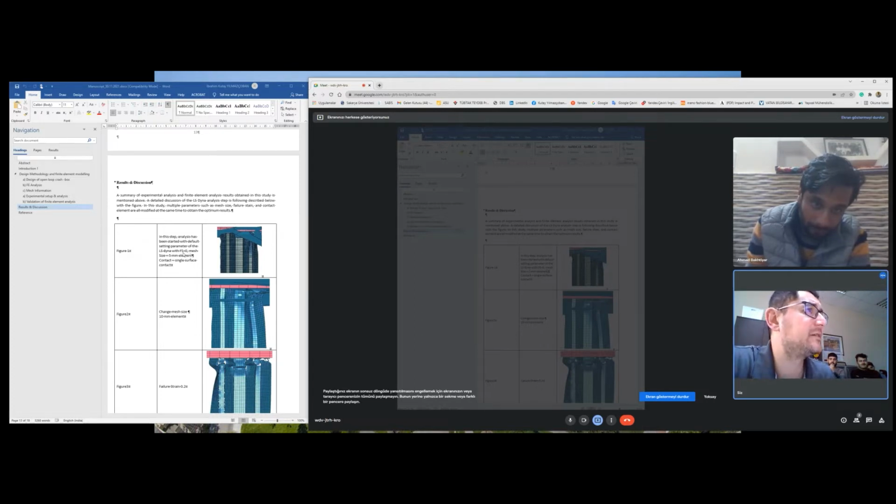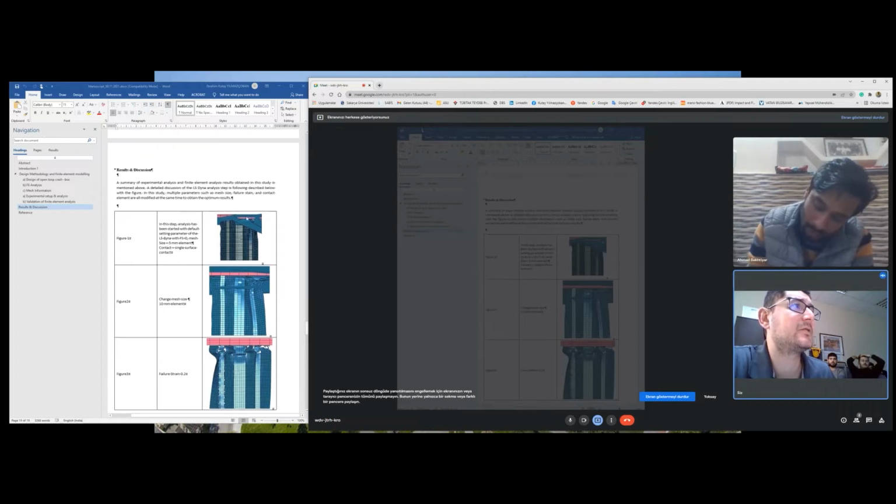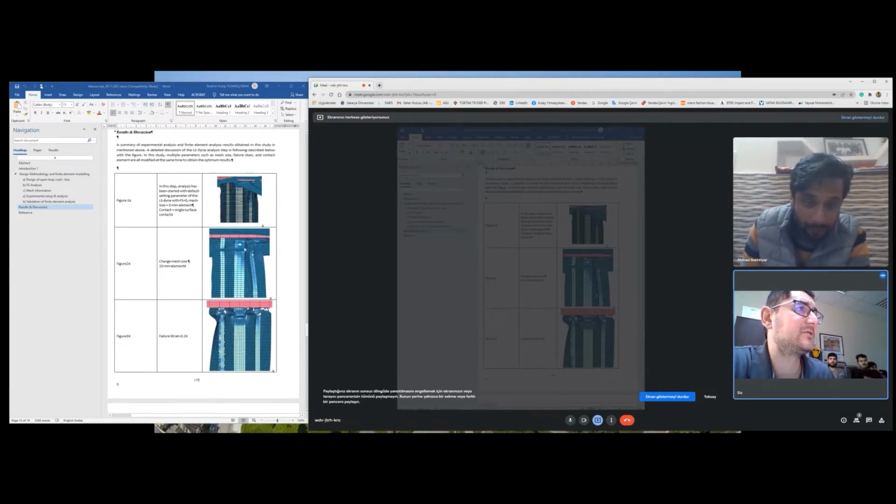Fs, friction or failure? Failure strain, right? Yeah, failure strain. Mesh size 5 millimeter per element, contact, single surface contact. Okay, there was a problem. You change mesh size, okay, it is going to decrease.